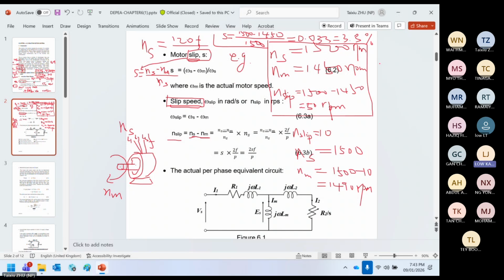If the question asks pole pair, the pole pair means I want to times two, correct? Yes, if the question tells you the pole pair, you times 2. But the good thing is, in our examples and the exams, we always give the number of poles, not the pole pair. If you read an article or some other reference and it says the pole pair is 2, then in this formula you cannot use 2. You have to use 4.